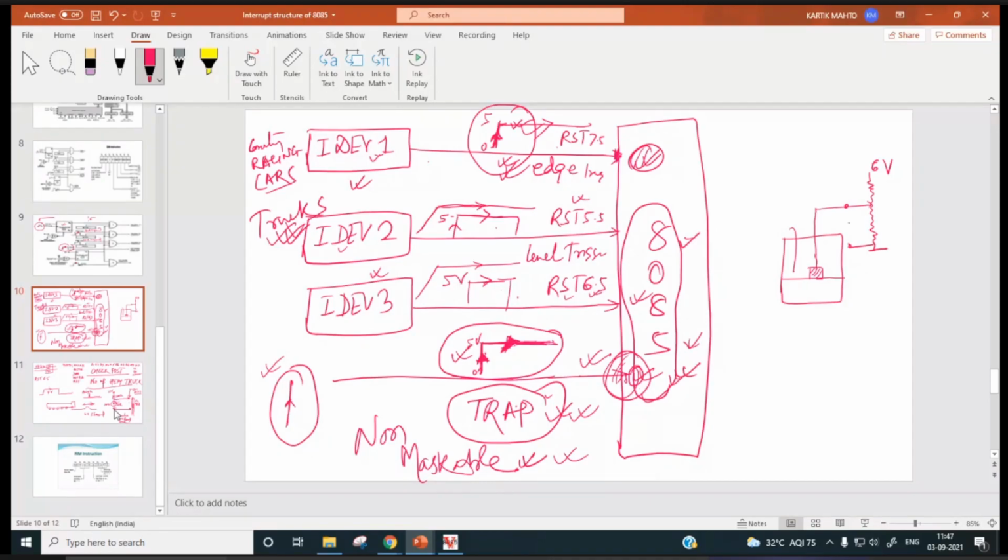Around say 2.5 volt. Now as the liquid level increases, the float will be over here, and this mechanical link will move up to this, and at that time this voltage becomes 5 volt. So the voltage is going to increase.